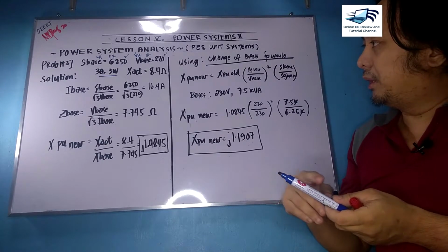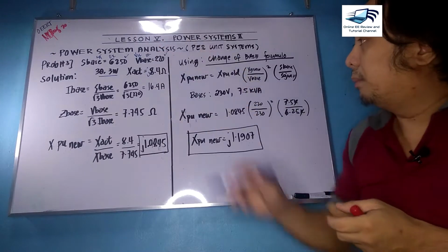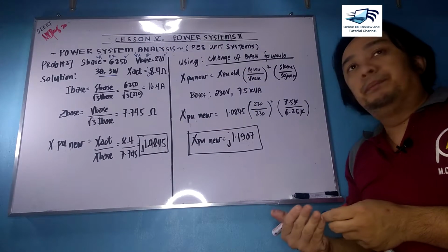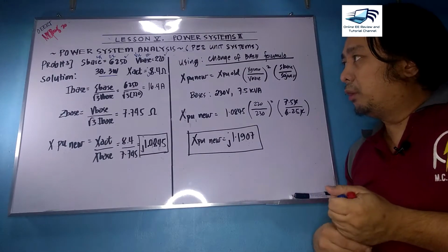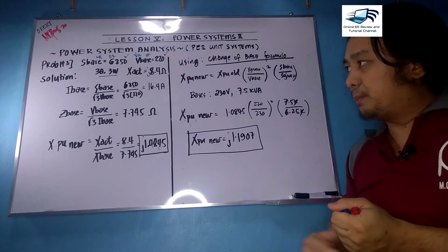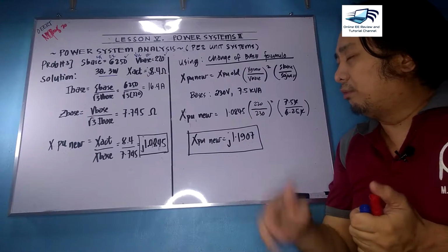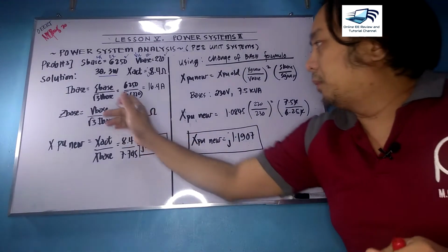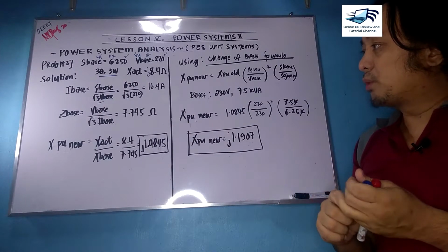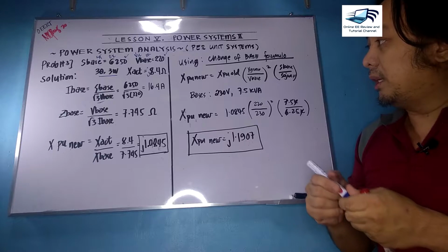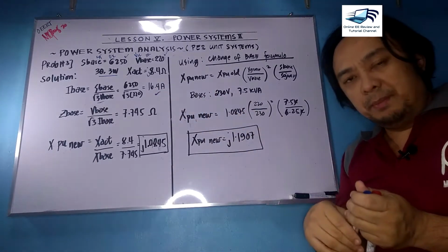And then we have here your X actual, which is 8.4 ohms. I need to have a J there corresponding to a reactance. Now we can substitute all of the values of your bases to get I base and Z base respectively. So here your I base is S base all over square root of 3 V base. The square root of 3 here corresponds to a 3-phase system. So you have 6250 all over square root of 3 times 220. The answer is 16.4.